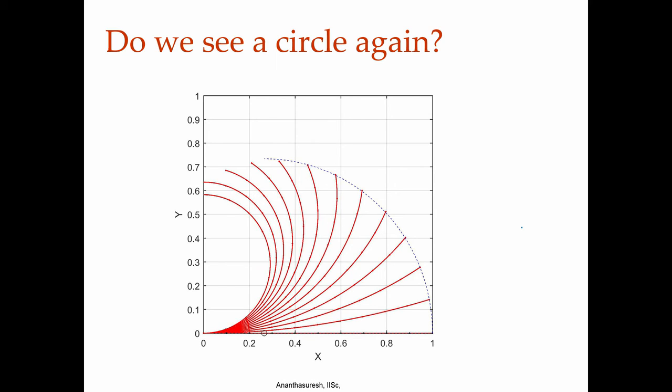So, here what I have taken is our elliptic integral as well as finite element analysis solution to plot for various moments. So, moment here is 0, here is some value and so forth. Again the values taken for this are what we had taken previously. E is for steel, length is 1 meter, cross section is 5 centimeter by 1 millimeter, like a strip of steel, and the load here was a moment load varied up to 3 Newton meter.